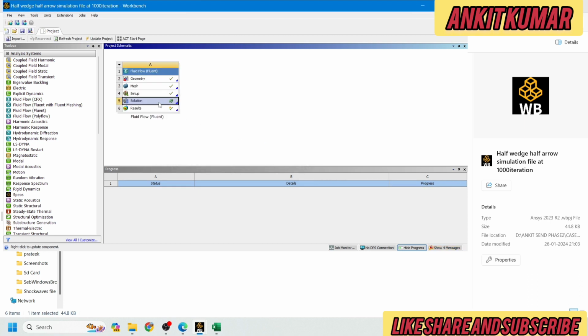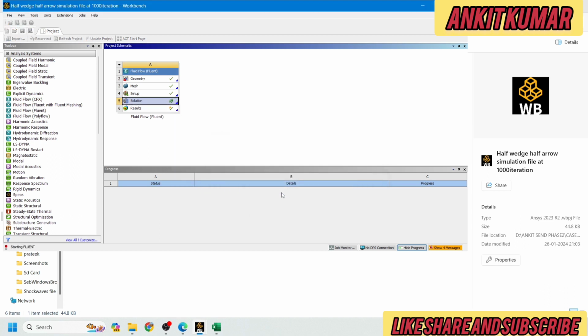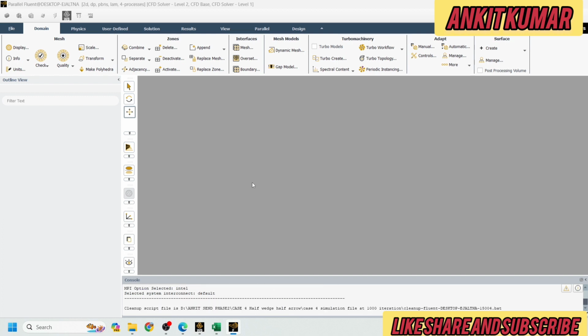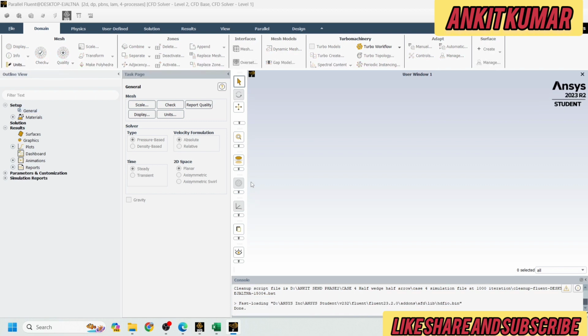Okay, right click on solution. I have already run the simulation. Right click on the solution, and it will load the ANSYS Fluent solver, and from there I will extract the different values by making different lines in the transverse direction at 80 mm, 130 mm, 210 mm like this. After making the lines, I will extract the values. So once it gets loaded, I will extract the values.